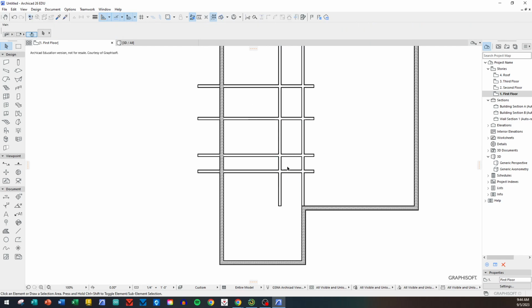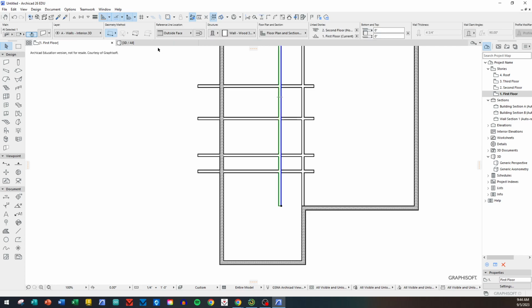Okay, so this wall is the bearing wall through the house. This right here is the closet, and there's a linen closet here and a linen closet there. Both of those are just about 2 feet deep. So I'm going to go right here and go copy, multiply right there, good. And I'm going to move that in this way exactly 2.